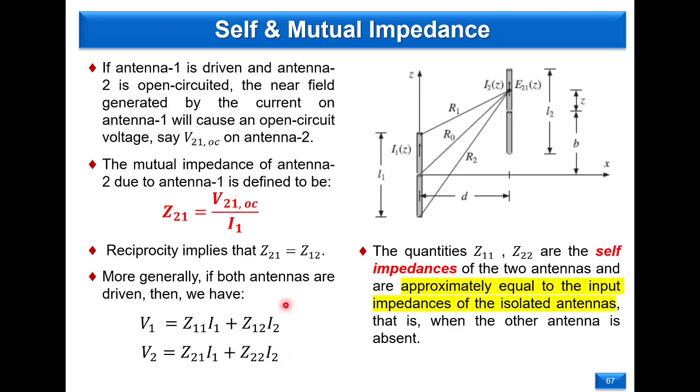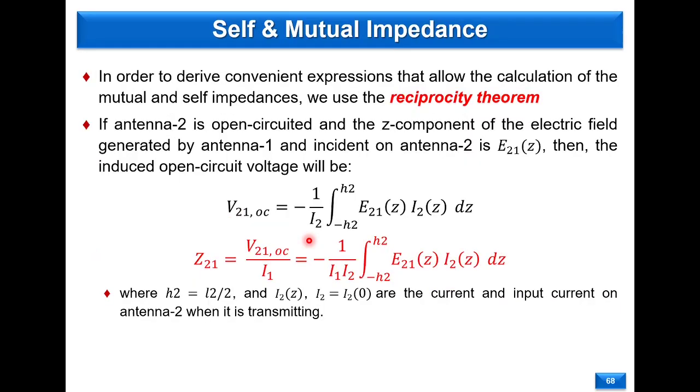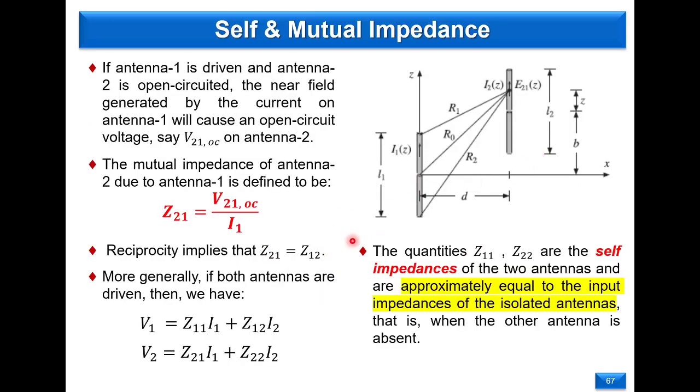So this is the expression when we have two antennas. If we have three antennas, we'll add more terms of mutual coupling, but as you would expect, if we have another antenna here, the coupling between 1 and 3 will be weaker than the coupling between 1 and 2, so we can neglect the coupling to the next element. So just keep coupling to one element to the right, one element to the left, or just the nearby antennas, not go for the second row. And one thing here from the reciprocity theorem we talked about: Z21 equals Z12.